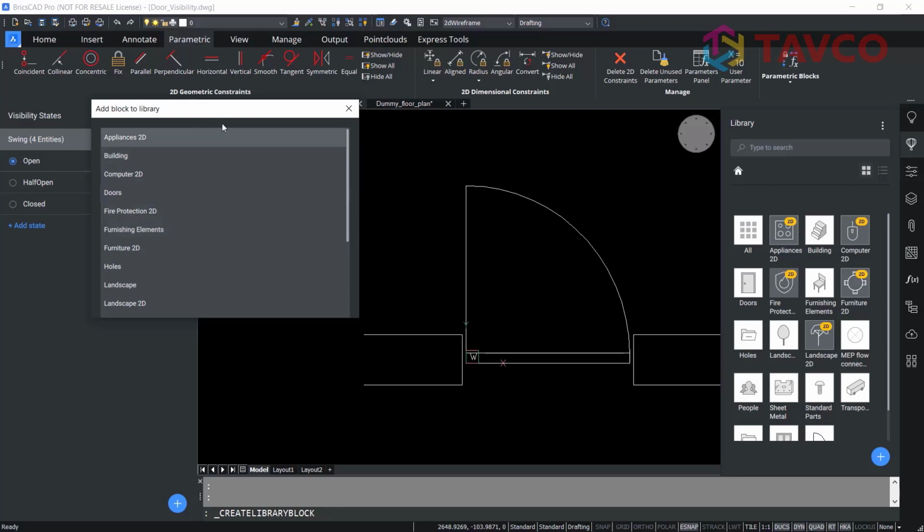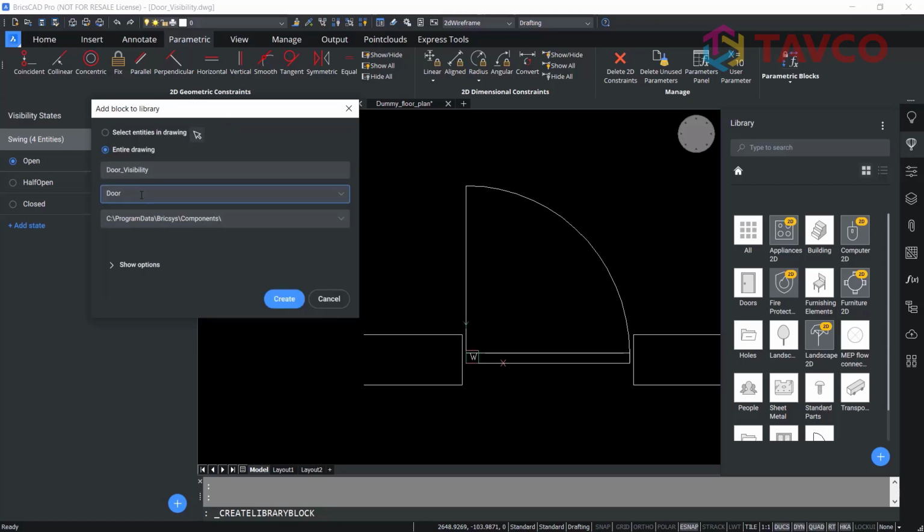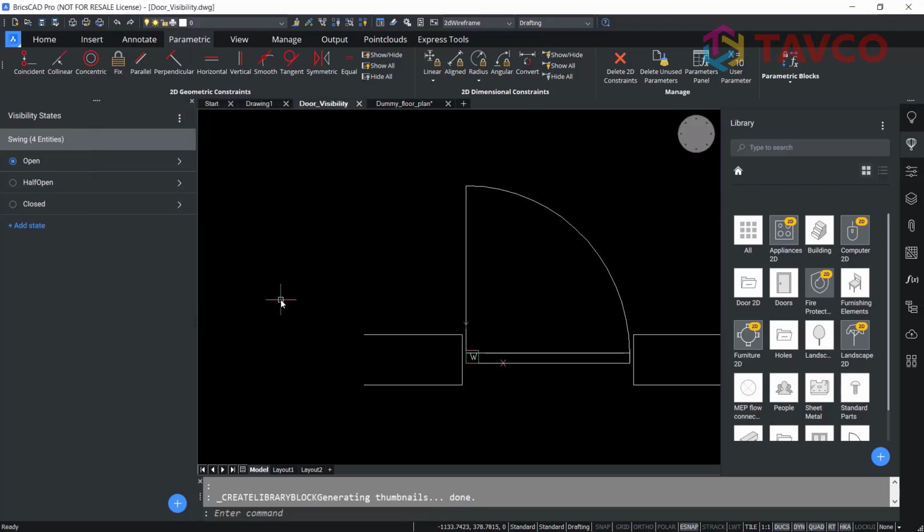So let's pick outside of that list and continue to edit and call it 2D. This folder doesn't already exist, so it will be created on the fly. We do want it to create it in the same components folder as the remaining library components, so select the Create button. We can see that the new folder appears here.